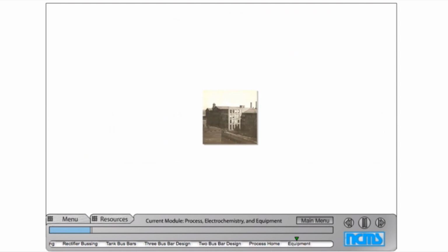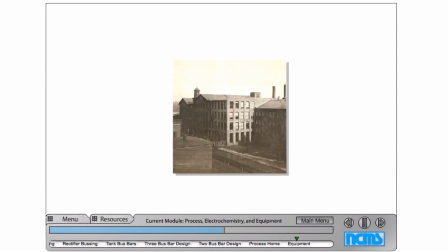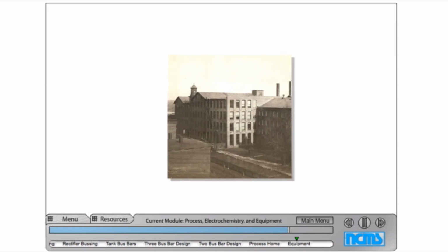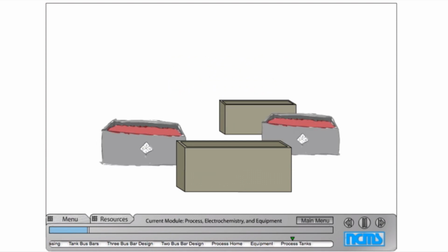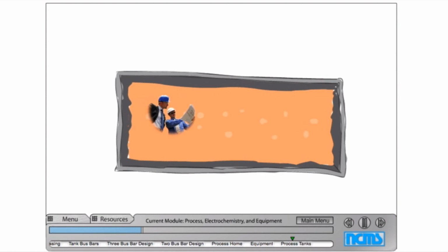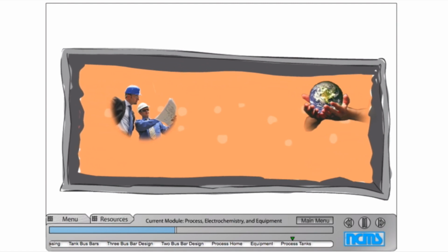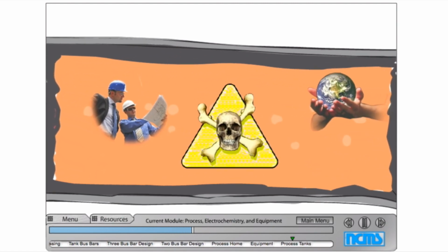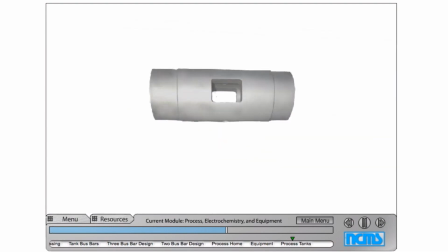A plating shop has a lot of equipment needs, ranging from the very mundane to the very complex. The chemical and electrical requirements of such a shop also feed into what equipment is most necessary. A hard chrome plating bath requires a specialized tank, and usually some support tanks for related activities. The tank is a very major consideration. Chromic acid is serious stuff, and keeping a tank of it heated and ready for plating requires careful planning by qualified engineers and tank designers. There are huge environmental and safety issues associated with tank leaks, not to mention the personal hazards of working around such toxic and corrosive chemicals.